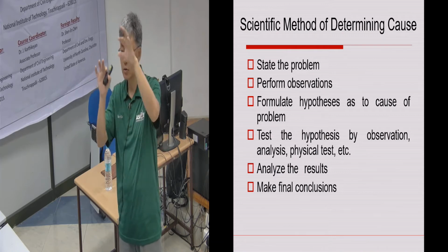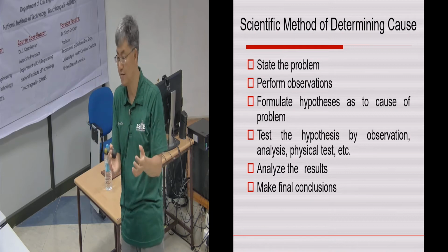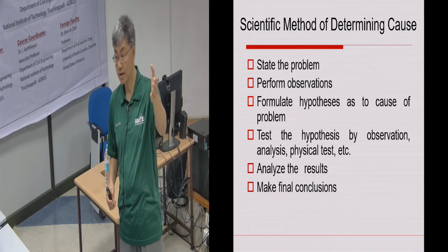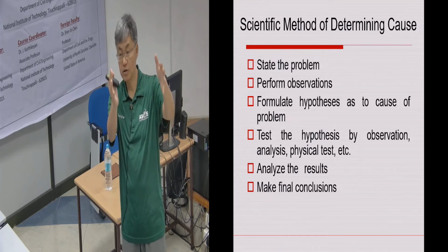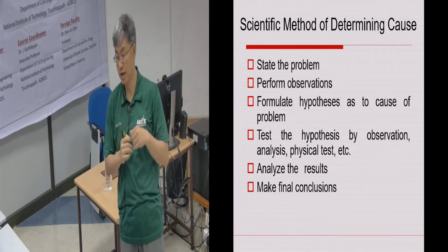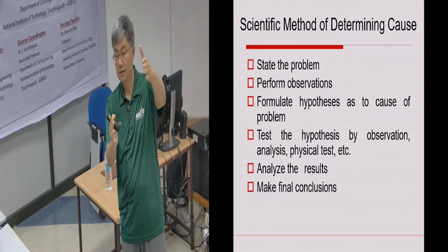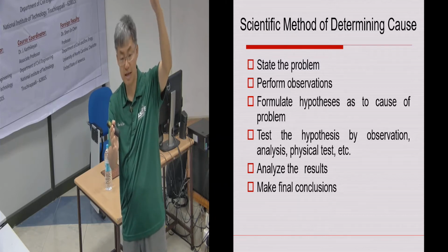Throughout that process, you start to organize your evidence. I found a cracked window. That cracked window was probably due to the window frame being deformed. So what caused the window frame to deform? Either part of the wall has collapsed, or it was pushed down because the beam on top has heavy loading.